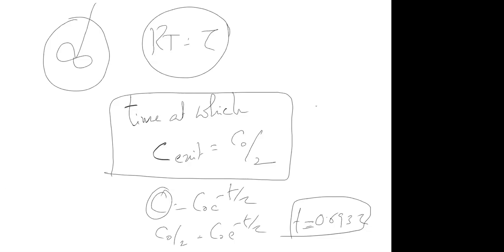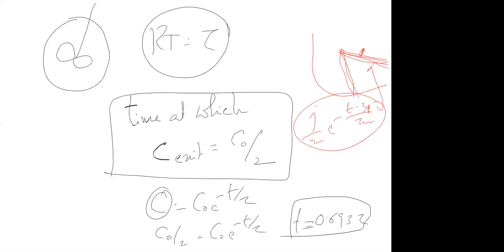Segregation models, yes, these are there. Dispersion model and tanks in series models are there. Another doubt is in RTD of CSTR and PFR combined. What does the equation 1 by tau equal to? It represents the T minus tau equation. This is represented by 1 by tau m equal to e power minus (t minus tau p) by tau m. So when you put tau equal to tau p, you will get 1 by tau m. That is the height of the curve.